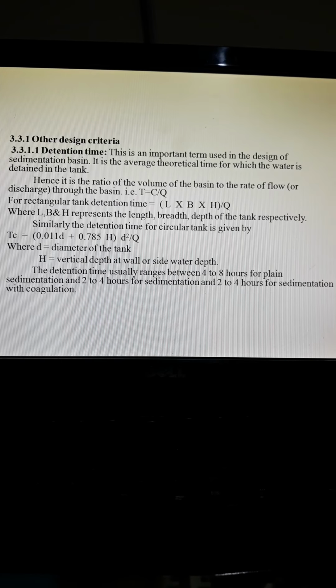The detention time usually ranges from 4 to 8 hours for plain sedimentation and 2 to 4 hours for sedimentation with coagulation.